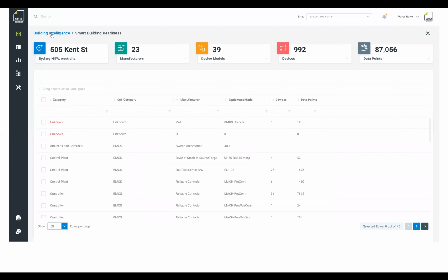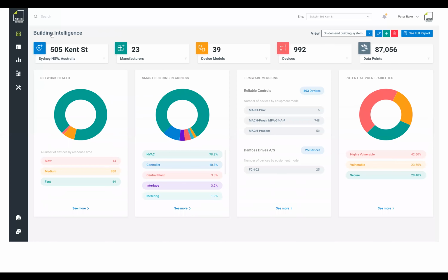It could be even Modbus. So typically BACnet is port 47808 on BMS systems. Modbus is port 502. So we actually get into the detail here, and we're able to give you immediately a compatibility of, is your building ready to be connected?